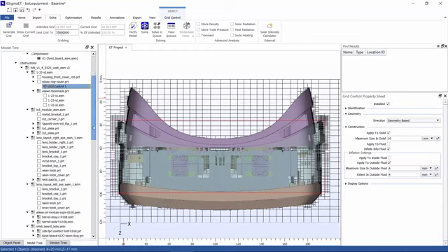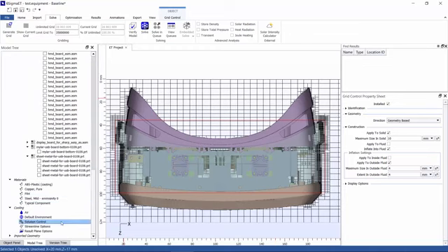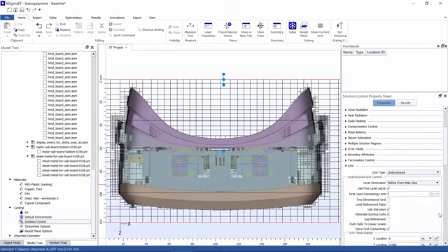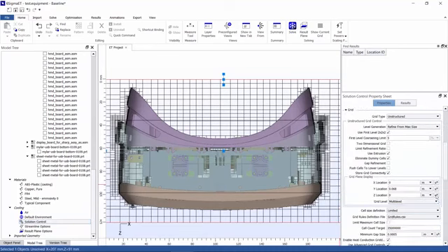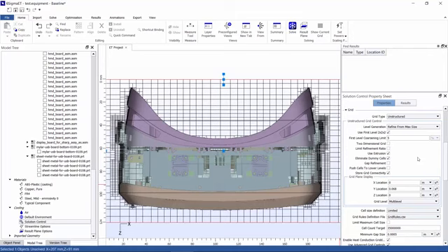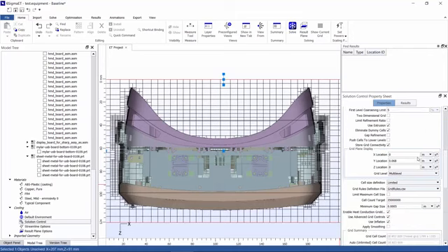And we also have advanced grid controls. And these are global grid controls that can be controlled using the solution control. If we navigate to solution control and then the grid section, we see a few important options here. So the first we have is the limit refinement ratio. And this will allow you to limit the ratio at which the grid goes from refined grid to a more coarse grid. So that's one thing that you can do to globally adjust your grid control there.